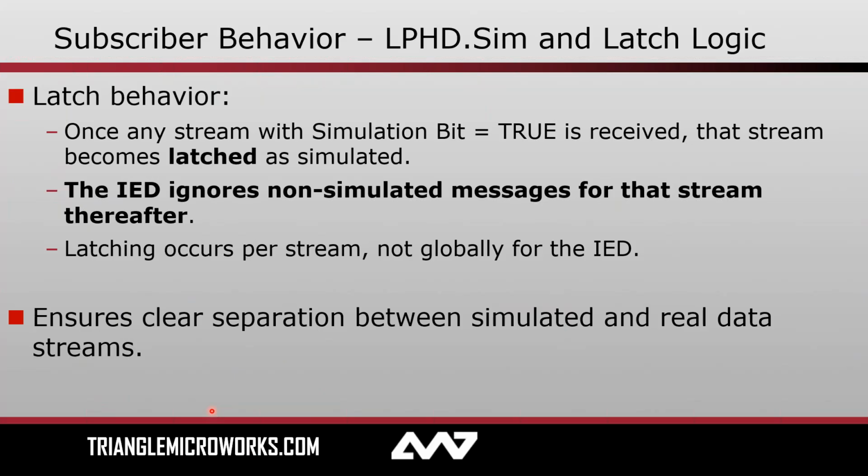That device will continue to process and use streams from the real publishers, which don't have the sim flag set, until the point at which it sees a simulated stream. And then that particular stream will be latched onto, if you will, and the real stream coming from the physical IED will be ignored from that point forward until LPHD Sim is set back to false.